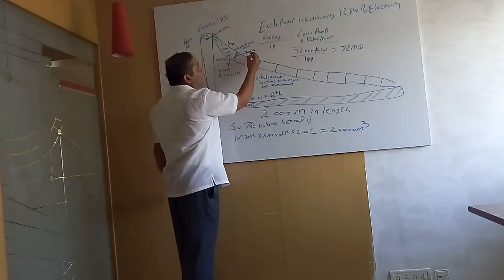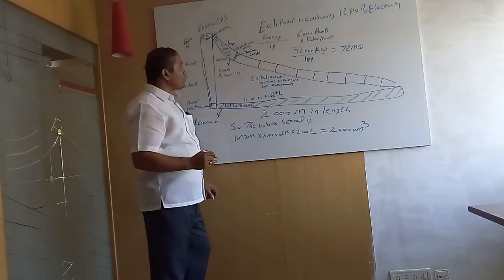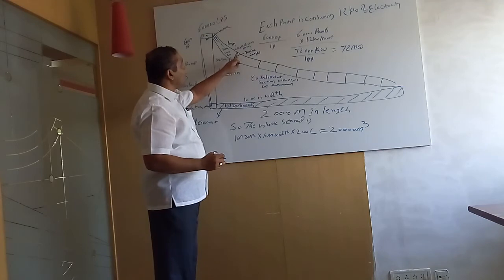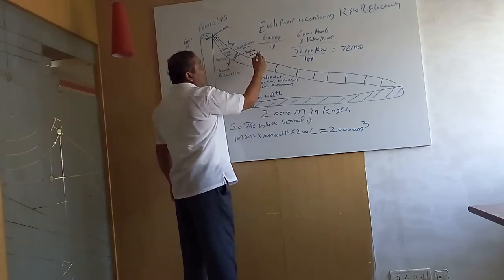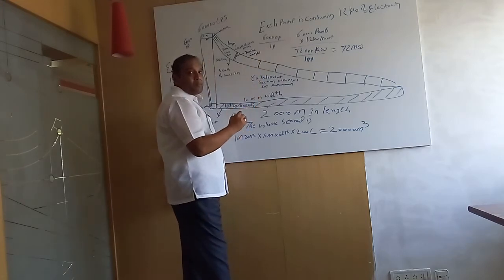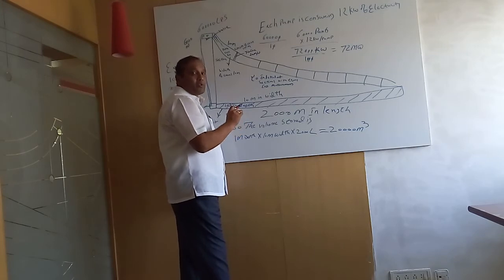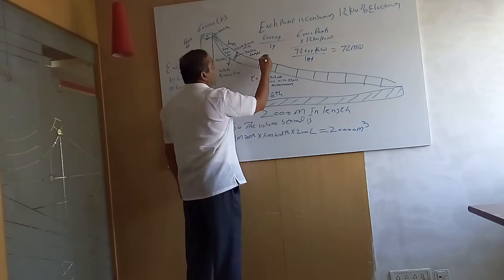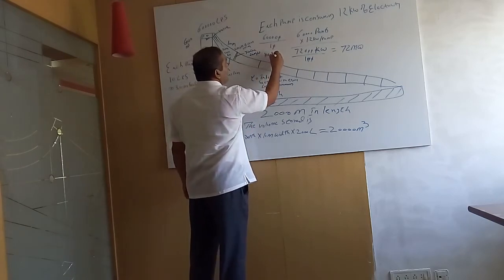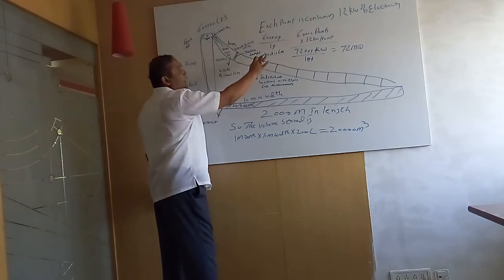So here the turbine capacity is 20 megawatts in installed capacity. This 20 megawatt turbine is rotated at 60 rpm only. The 60 RPM is having 24 poles, and 24 poles will rotate at 60 RPM. So here the head is 6 meters because the depth of the canal is 6 meters.